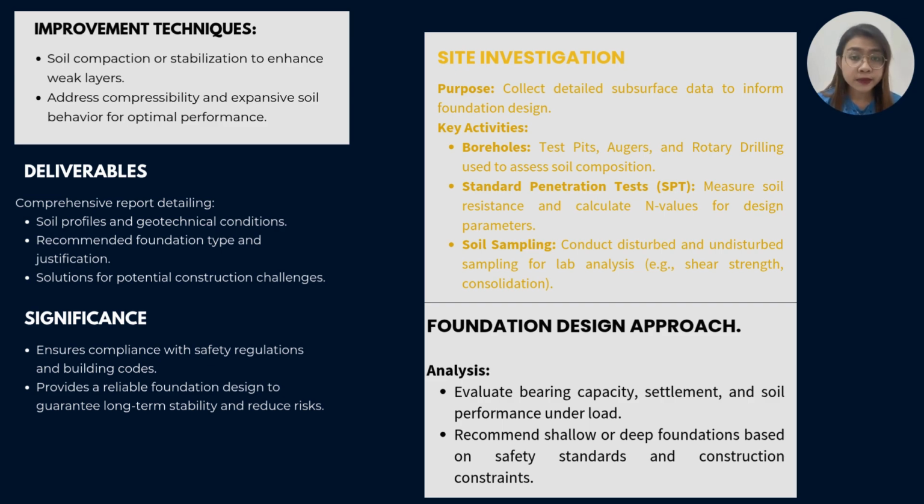Next are the improvement techniques. First is soil compaction or stabilization to enhance the mixed layer. Then we address compressibility and expansive soil behavior for optimal performance. Next are the deliverables, a comprehensive report with three parts: first, soil profiles and geotechnical conditions; next, recommended foundation types and justification; and lastly, solutions for potential construction challenges.